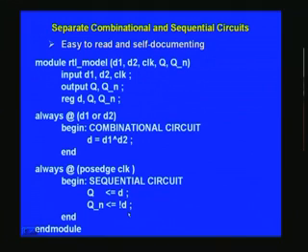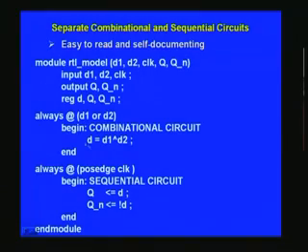A module is something like a black box. You have a block diagram which you are already familiar with. It will have IOs, and that's precisely what you have here. So that block can be given a particular name, and the block itself we call here a module. And once you have a module, you should signal to the tool that is going to process further by another corresponding signal called endmodule. Note that there is no gap between end and module, it is a single word. So module, endmodule, this is a vital thing that you have to keep in mind.